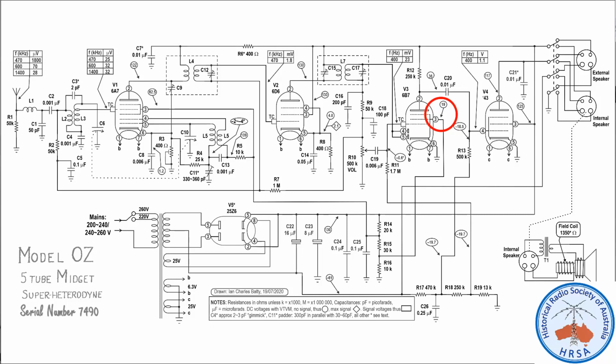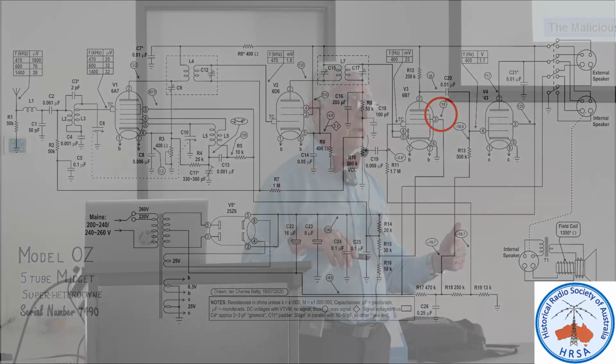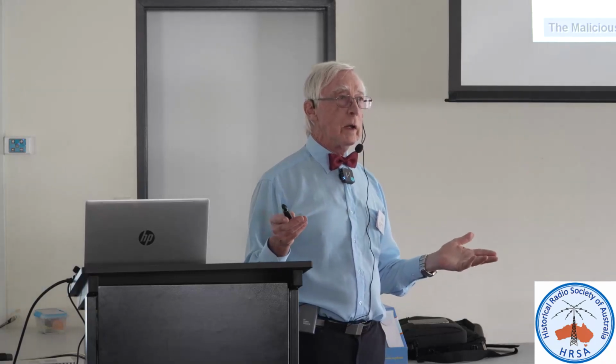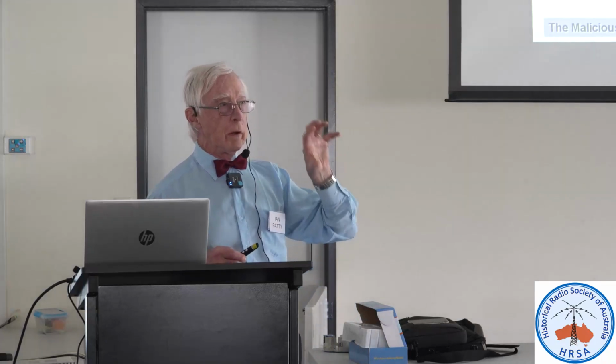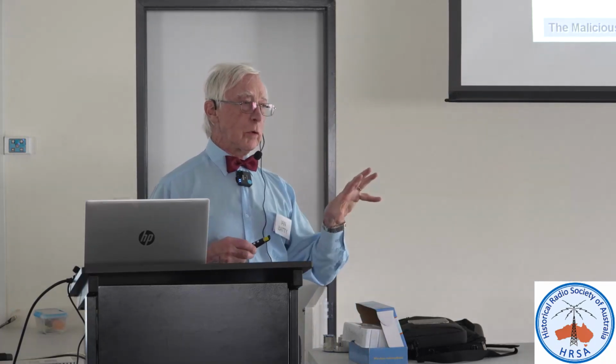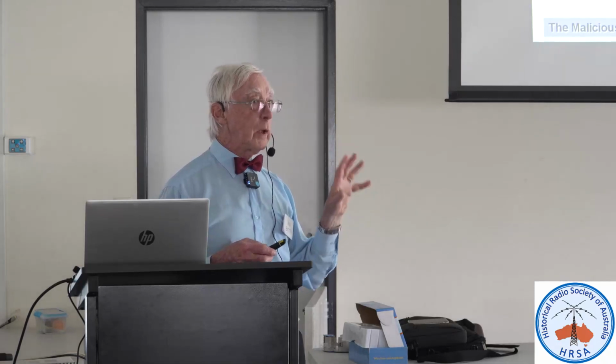So in this circuit, although there's no screen bypass, the fault would have been revealed around about on the 6B7 grid. You may notice that the voltages in this circuit are pretty low, 38 volts at the anode and then 19 at the screen. Looks wrong, but checking on the circuit, that's exactly what it's meant to be because it's working from quite a low HT. The circuit still gives heaps of gain, it's just that those voltages are unusual. Again, know your beast, don't take fright at abnormally low or high voltages from what you expect because the circuit may be working perfectly, and this one was.